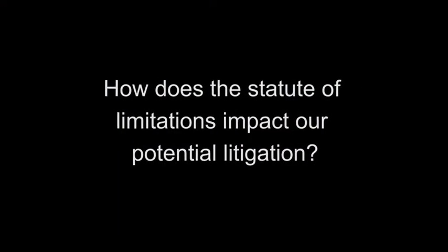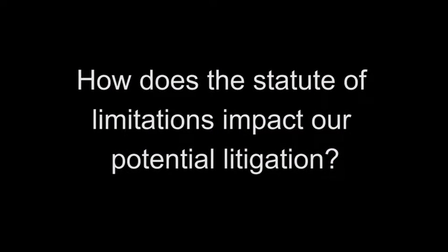I think it's very important that construction defect litigation cases involve something called the statutes of limitations. That's a period of time, and it varies from state to state, when you can bring action against a designer, against the builder, against various subcontractors. So in New Jersey, for example, the statute of repose is 10 years. So you have a 10-year period in which you can bring action against the builder or the developer in the communities.